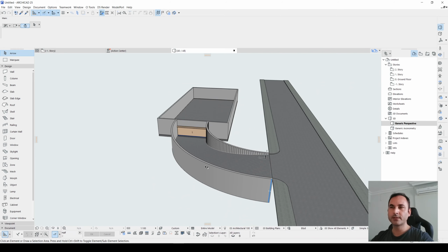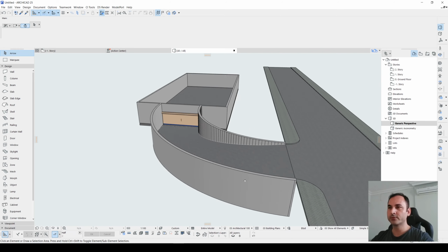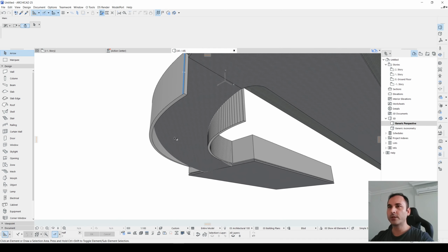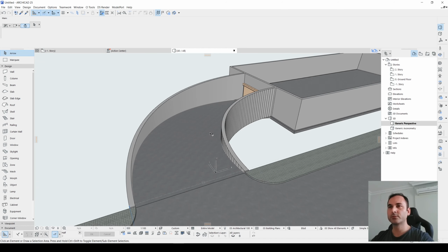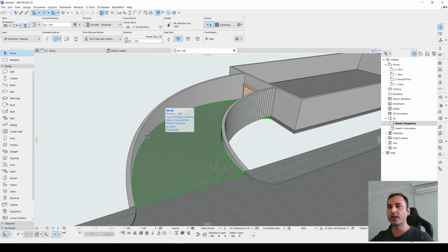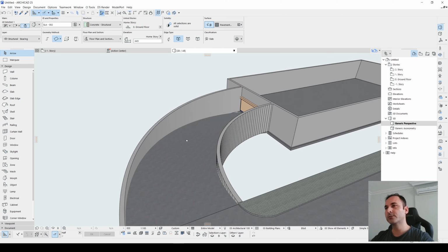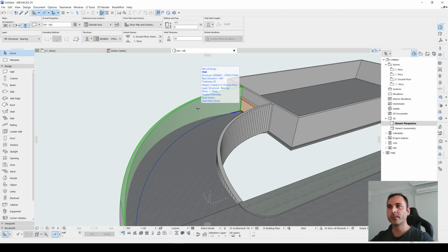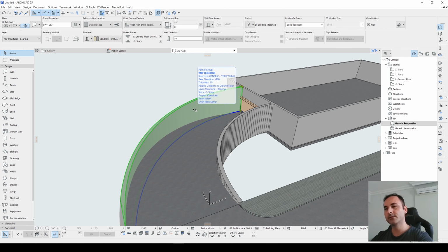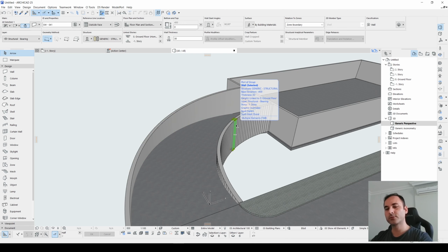Now we will cut this bottom part of our walls. To achieve it, we will use Boolean operations, but we don't have any kind of Boolean to cut it out. Therefore, I'm going to use this, but I don't want to create another one. Of course, you can create yours. To make it shorter, I will revert this position and also reverse this position too.